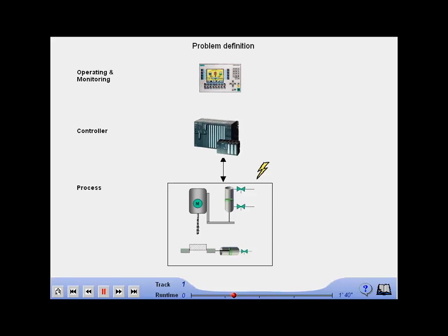A standard alarm system informs the operator of a symptomatic fault by a display on the HMI device. Now, to determine the cause of the fault, for example, which missing step enabling conditions are holding up the process, you need a programming specialist who has to analyze the user software with a programming device. This sort of procedure usually results in long standstill times.